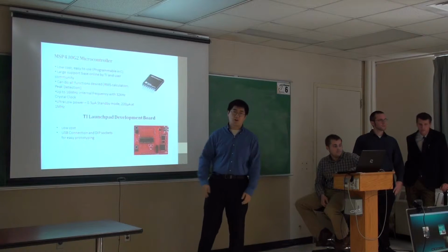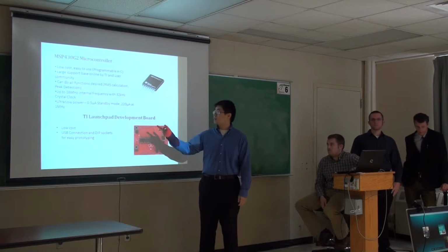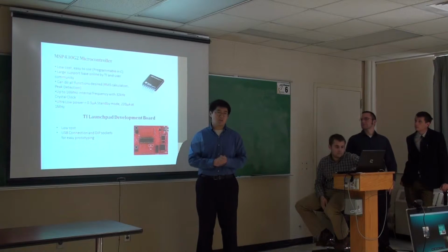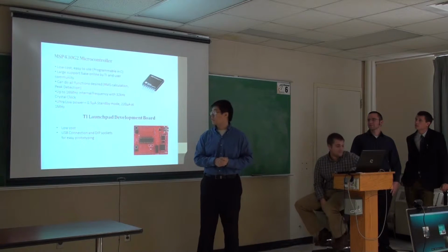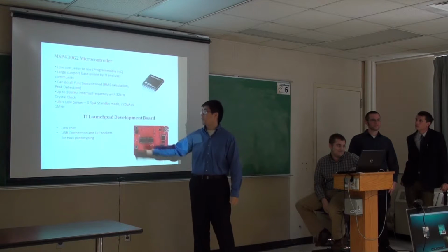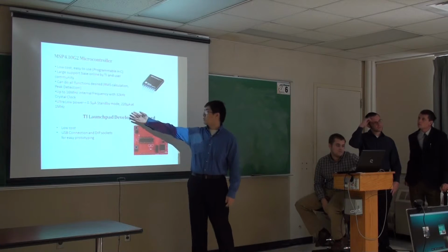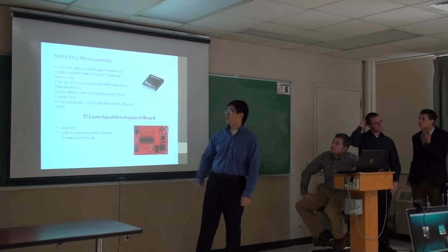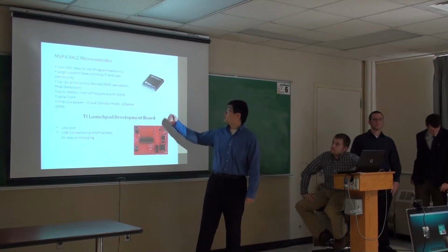We can code it to do RMS calculation and peak detection, and it's got a 32 kilohertz crystal clock built in. To meet our 100 hertz bandwidth, we'll probably need a 500 hertz Nyquist frequency, which is way past what we need, so that's perfect. Once again, it's low power, and it consumes 220 microamps at 1 megahertz. We're probably going to be running the clock at maybe 500 kilohertz, so that's pretty good.